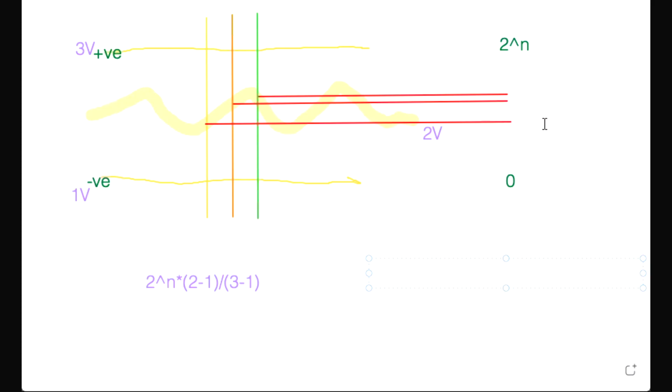So now bend angle, which was change in resistance, would now turn up as a change in voltage, which would then turn up as a change in the value you get from your A to D converter. Yep, and then you just do some maths to find the voltage and some more maths to find the resistance.